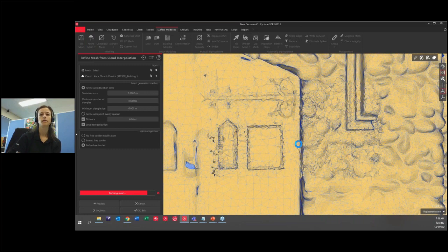Cool. And one more for now. Question from Caleb. Further to Rodney's question about the import of images: if you have a calibrated raw image, so it has the position and orientation of the photo, will 3DR read that information? Yes, I seem to remember you can import your calibration file in 3DR. I haven't done that in a while, but you can also calibrate it yourself in 3DR, if you take all the pictures in the right workflow. But if you do have calibration, you can import it. It's described in the help file how the file should look to import it straight in and what type of data it's looking for, so you can make sure you have a file that makes sense for 3DR.